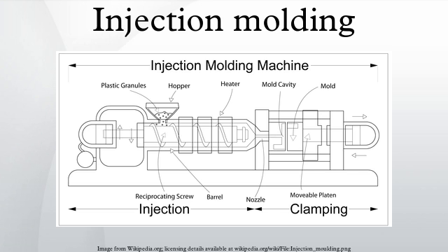Molds are generally made from tool steels, but stainless steels and aluminum molds are suitable for certain applications. Aluminum molds typically are ill-suited for high-volume production or parts with narrow dimensional tolerances, as they have inferior mechanical properties and are more prone to wear, damage, and deformation during the injection and clamping cycles. But they are cost-effective in low-volume applications as mold fabrication costs and time are considerably reduced. Many steel molds are designed to process well over 1 million parts during their lifetime and can cost hundreds of thousands of dollars to fabricate.